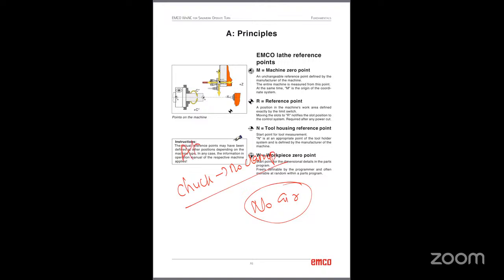So we will get a machine alarm if there is no air. This machine has a central lubrication system. This will provide oil to the guideways, ball screws and bearings. Make sure that the lubrication oil level is correct. The machine has a fully enclosed working area, with a door interlock system and an emergency stop. If you open the door, the machining will stop immediately.